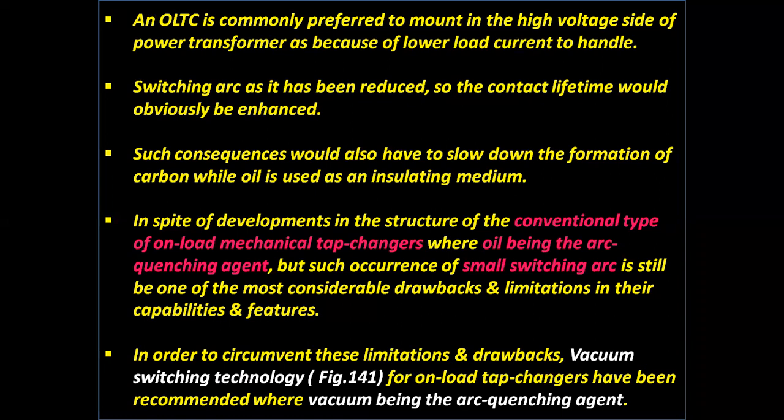In order to circumvent these limitations and drawbacks, vacuum switching technology, figure 141, for on-load tap changers has been recommended, where vacuum is the arc quenching agent.